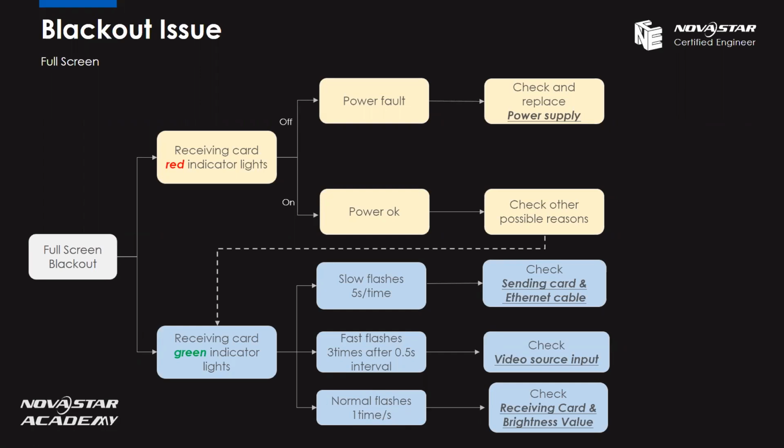But if in this case the screen blackout issue still occurs, we need to check some other possible reasons. Like we need to check the receiving card firmware program file, or the receiving card RCFGX file, and see if there is something wrong with these two files. And also, we need to check the brightness value. Make sure your brightness value is not 0%. And also, make sure in the software, the screen control settings are normal.